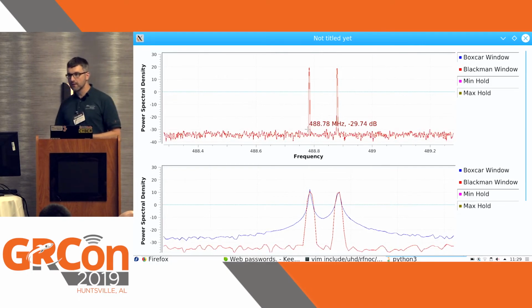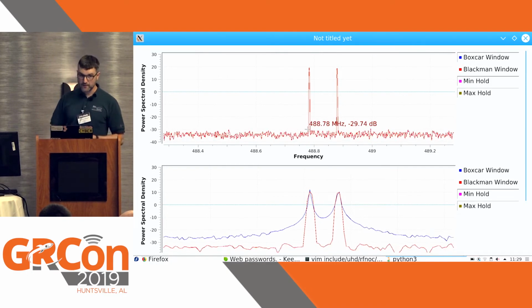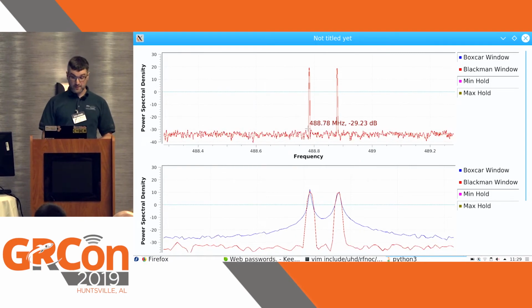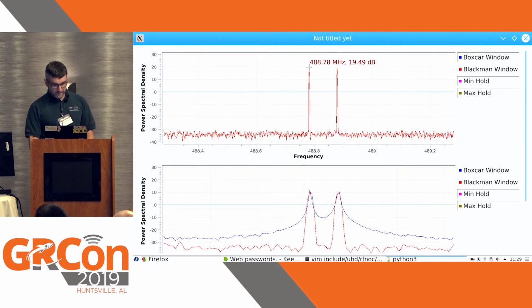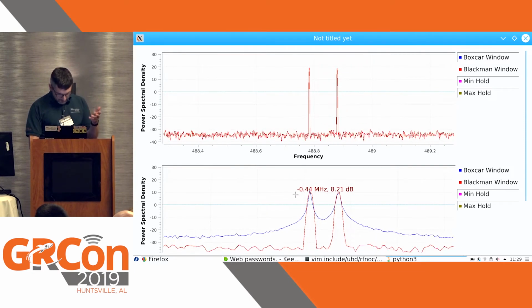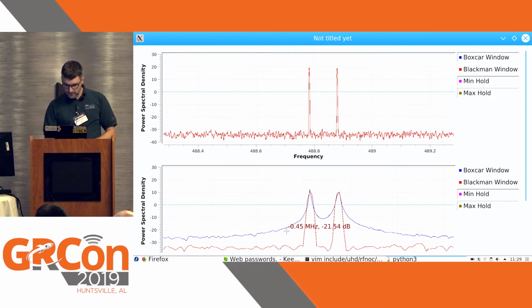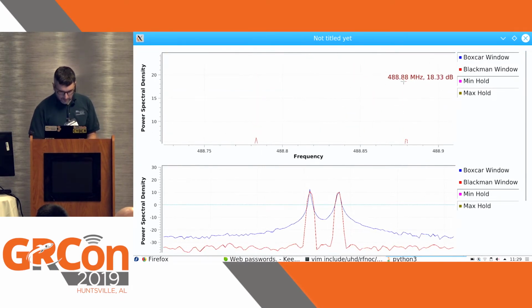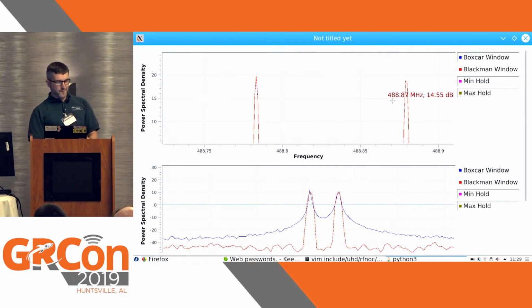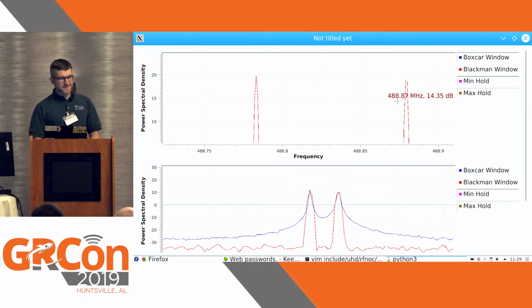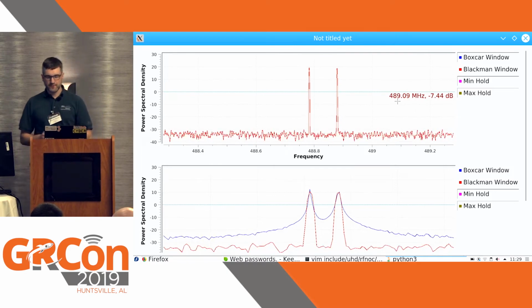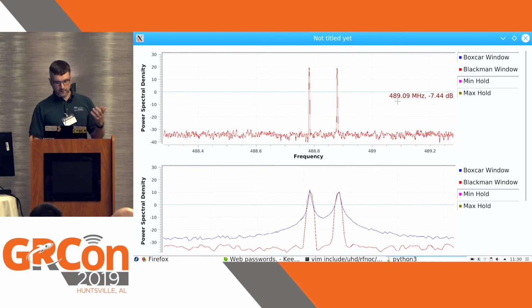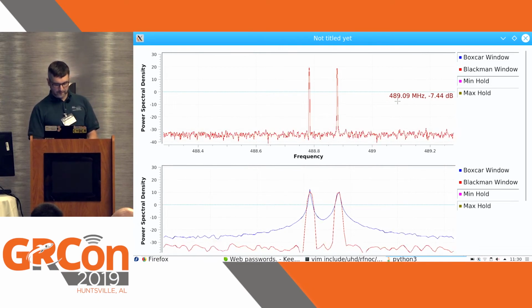Because the correct answer to the question is, what is your definition of the signal to noise ratio? Because I said I put in the exact same signal twice. This here is 50. Here, if you go by your logic, it's 40. And here, you have to zoom in to see that, but this guy is also a little bit lower than that guy. So this would be 50, and this would be like 47 or something. Doesn't really make sense, okay? How can the signal to noise ratio be different? And that's because the parameters of my spectral estimator actually matter for this case.